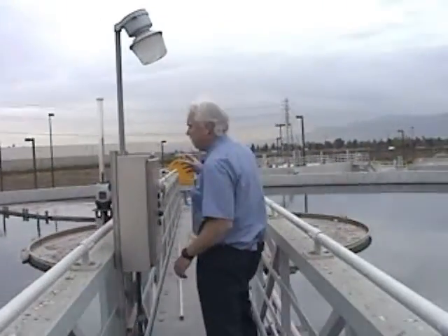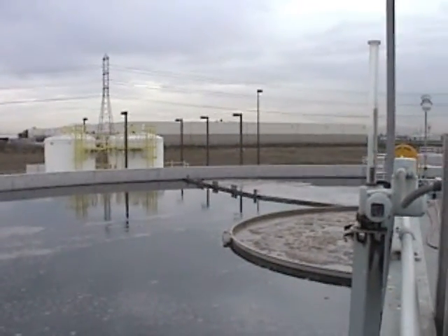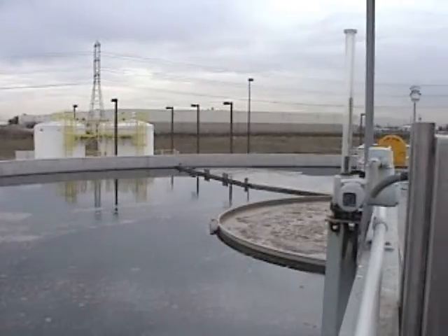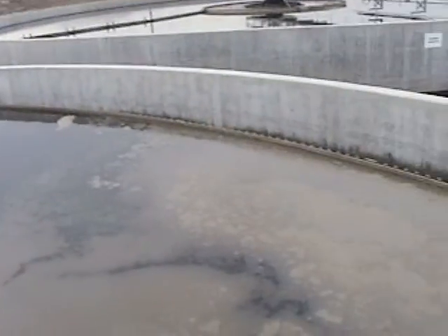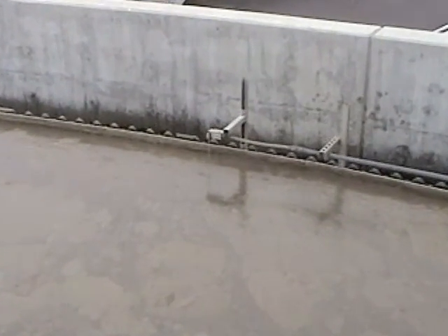And it's controlled by the sweep out there. What the sweep will do is, as it comes around the secondary clarifier, it hits a little whisker switch right there. You can see it just on the surface of the water. When that hits that switch, it will begin to lower the skimmer. I'm doing it manually right now. But what will happen is this skimmer will rotate down and begin to take liquid into the trough and skim off the surface of the clarifier.